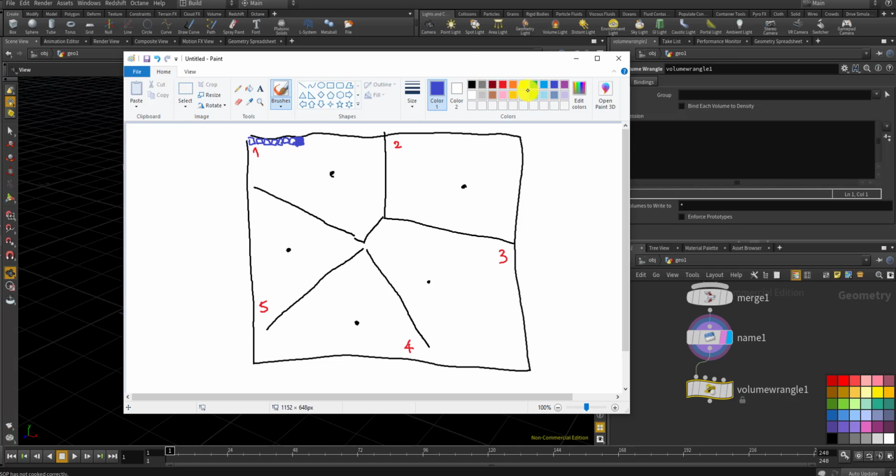first you need to calculate the distance from yourself on the point on the volume to each center point for the Voronoi cells. Get the distance. Will be D1, D2, D3, D4, D5, and see which distance is the minimum.